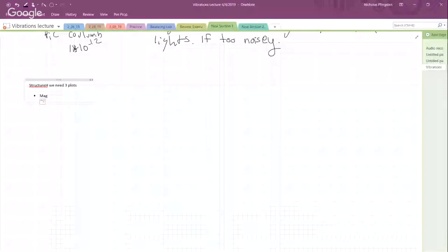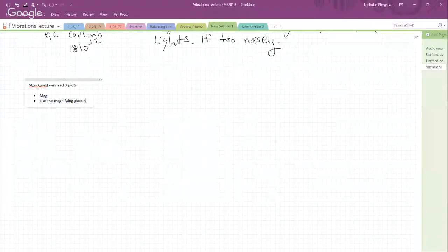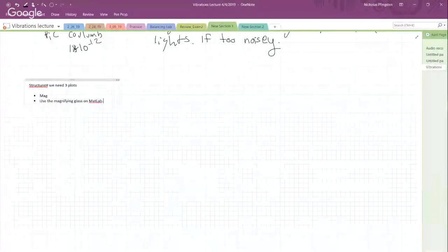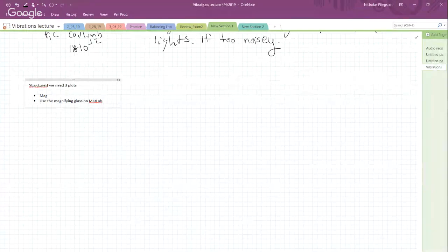Here we go. We can do the same thing here. Zoom in on this one. Even do a little bit better than that. Again, take the peak value here. That's going to define our frequency. Multiply that 7.98 by 0.707, that would define our bandwidth. Let me just go ahead and make sure I've got the right data for the other one.